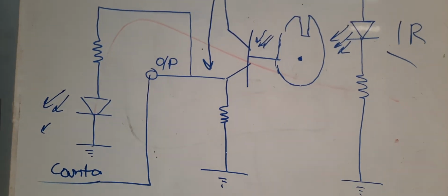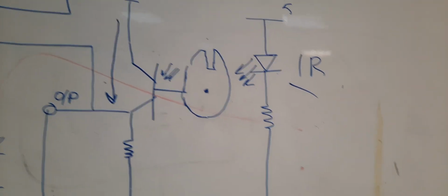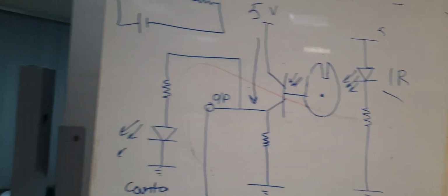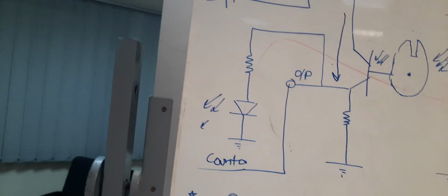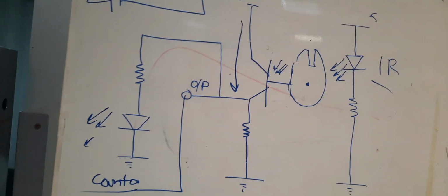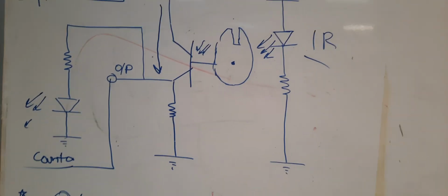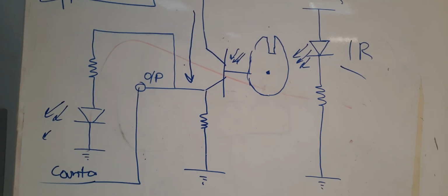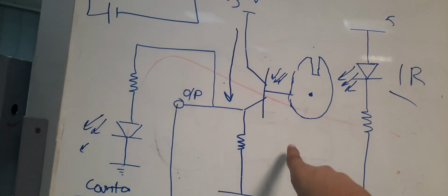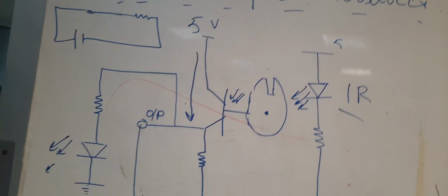So when the speed is increased such that it is not distinguishable with the LED, you can connect a counter. You need a DC motor, a potentiometer to control its speed, and obviously a slotted opto transducer to find its RPMs.